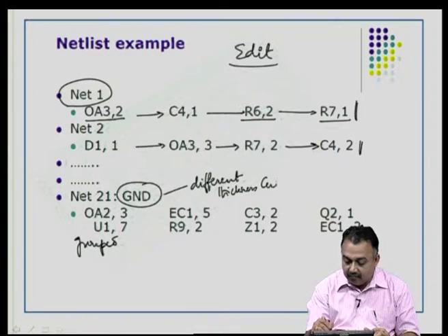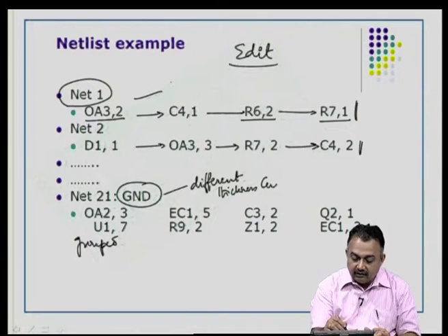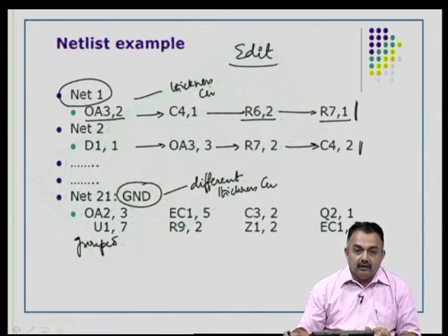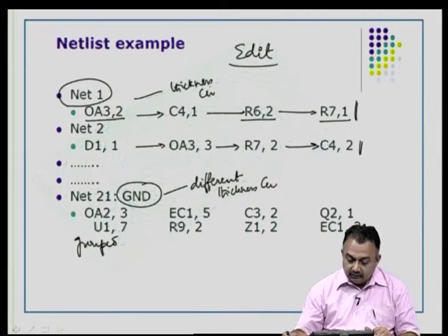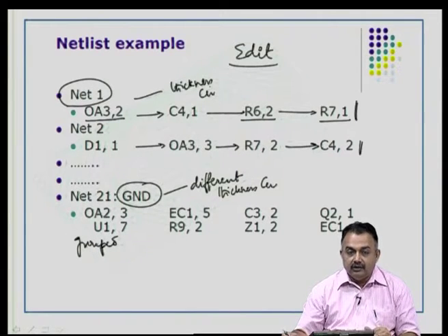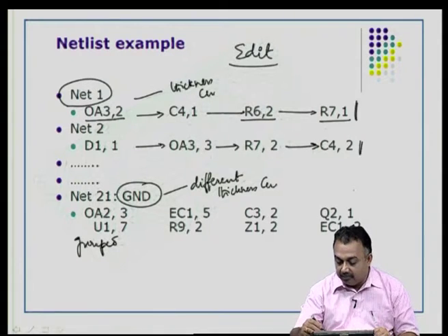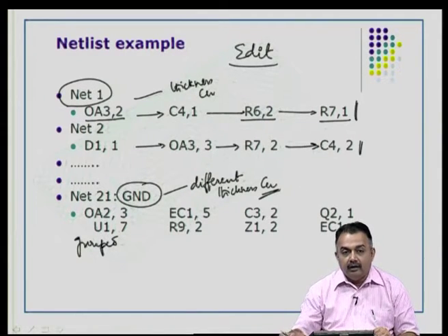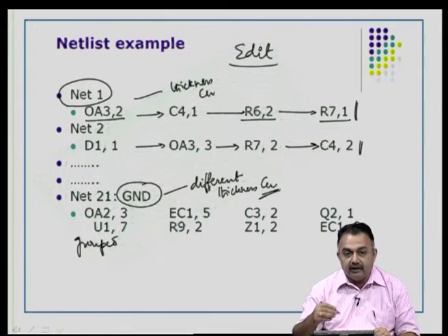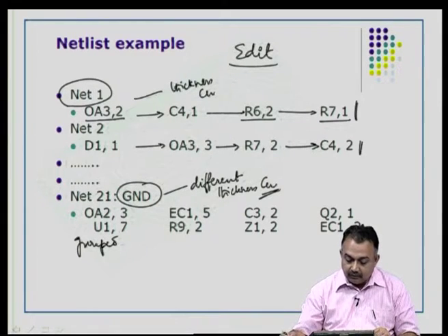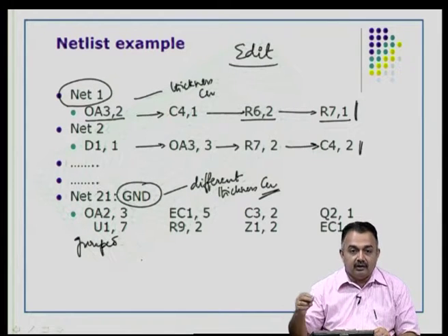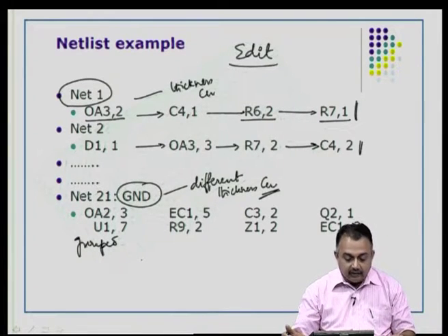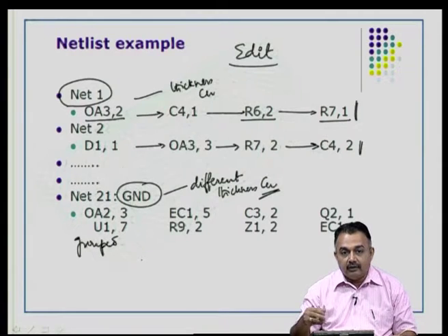Thickness of copper can be different. For these, the thickness of copper can be much less, because it is basically signal lines. Okay. So, in some cases you can use these as a heat sink copper, and therefore, you can have ground in different layers in a multi-layer board. So, you can interconnect with vias and push all these ground nets into a particular layer. So, this is the advantage of looking at a net list, and you can also edit them.